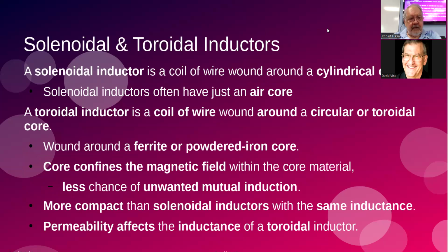So, like I said, you have two kinds. You have solenoids, which is just a linear coil, and a toroid, which is like a donut. In those cases, there's just wire wrapped around it with a number of turns. The inductance increases with the number of turns and the area within the turn. So the basic inductance formula is the permeability constant, the area, times the number of turns.